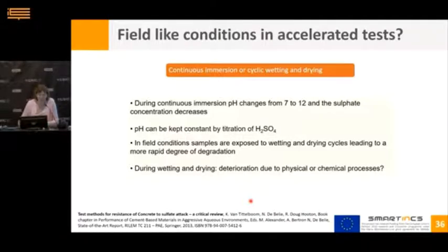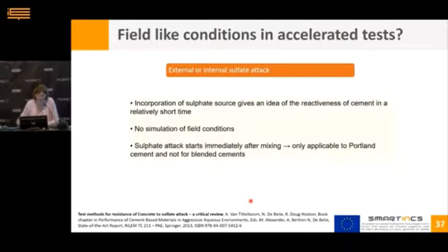Wetting and drying, as we told already, leads to a more rapid degree of hydration, and if you have the wetting and drying phenomena, then you should take care about physical and chemical processes. Looking into external versus internal sulfate attack, it's also a strategy, let's say, to include your sulfates already in your concrete mix in order to accelerate the process, because at that moment you skip the first phase where the sulfates should intrude in your specimen, because you already have them from the beginning. So in that way you can accelerate your test.